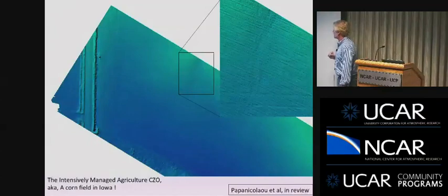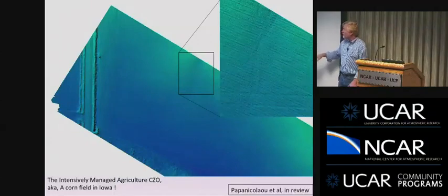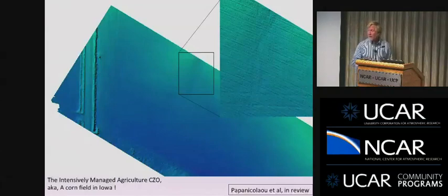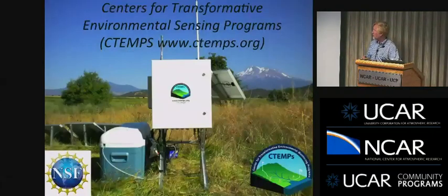That's pretty neat. And again, with this technique, we do need to have some ground control points. We need to know the elevation of certain places. So you do have to do some GPS surveying or total station surveying. But it's really quite easy and inexpensive for bare ground, or relatively bare ground. Okay, I'll leave it at that.